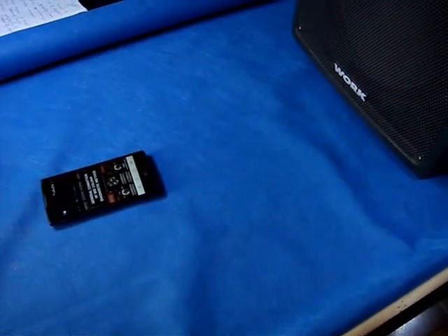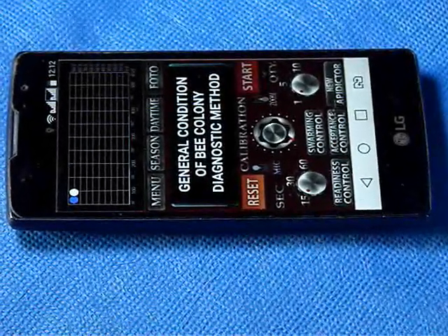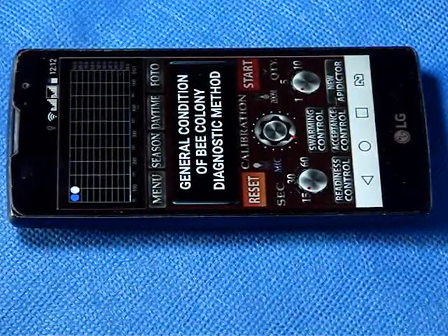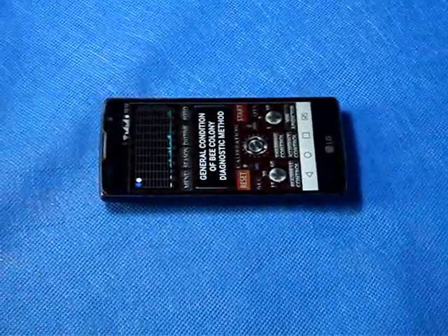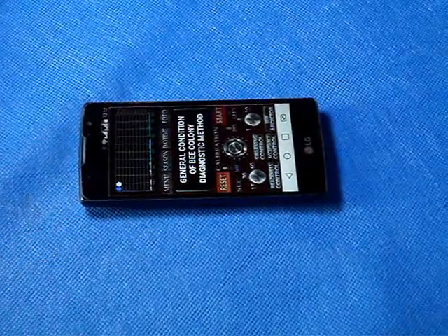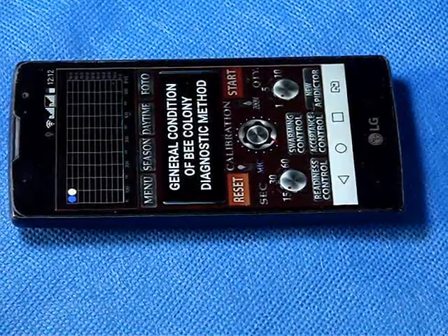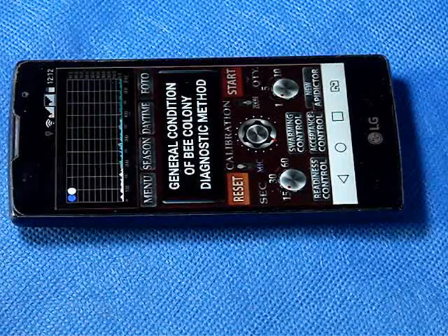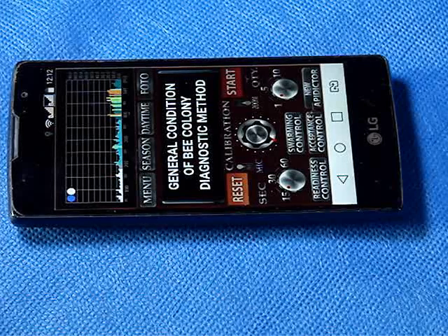So, the distance is selected, the smartphone is in the right place, and we begin setup. At first, we set up the internal microphone, so our smartphone is turned to the speaker with its microphone, in order to better perceive the signal. The sound volume of the acoustic system should be set so that we can see the picture of sound at about 30% of the scale height.